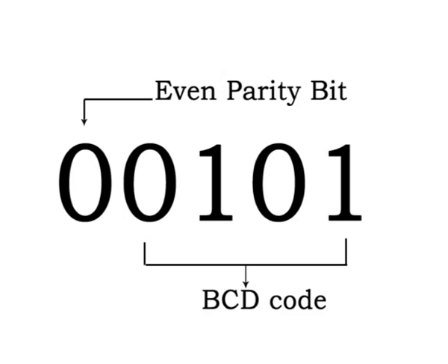Now, let us assume that an error occurs in the third bit from the left, that is, the 1 becomes a 0. When this code is received, the parity check circuitry determines that there is only a single one, that is, an odd number, when there should be an even number of ones. Because an even number of ones does not appear in the code when it was received, an error is indicated. An odd parity bit also provides in a similar manner for the detection of a single error in a given group of bits.